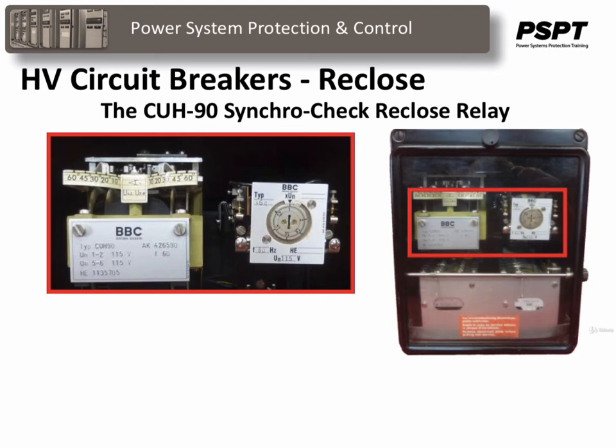So it's the job of the relays that are associated with a breaker to provide the various checks and balances needed to reclose a line into circuits. For example, if we have one breaker tripped and on either side of the breaker it's energized but out of synchronism, you certainly don't want to reclose the breaker. It would be the same thing as closing into a dead short if it was out of synchronism.